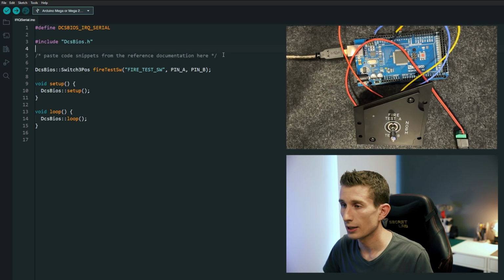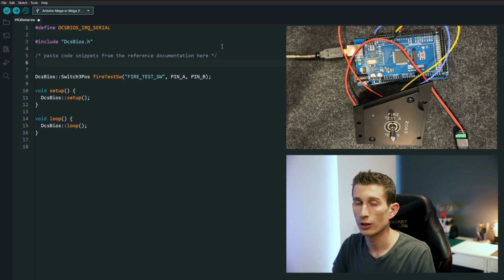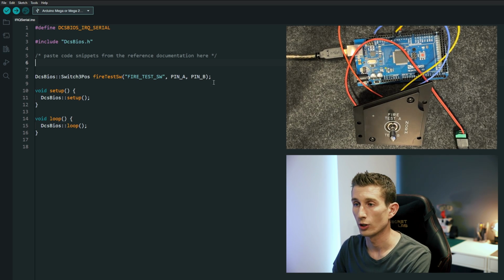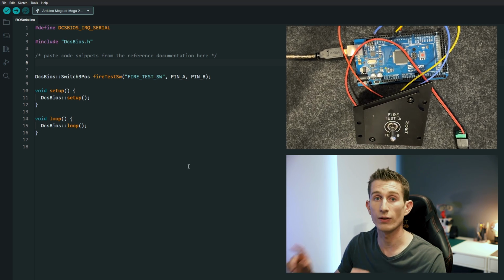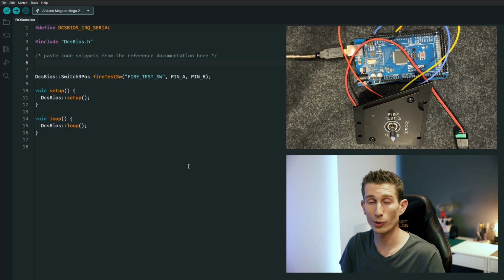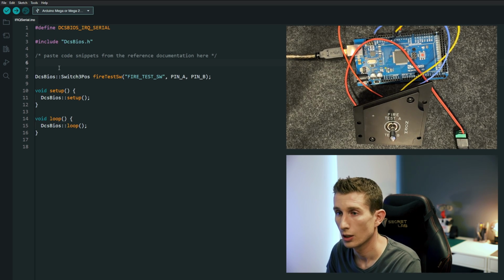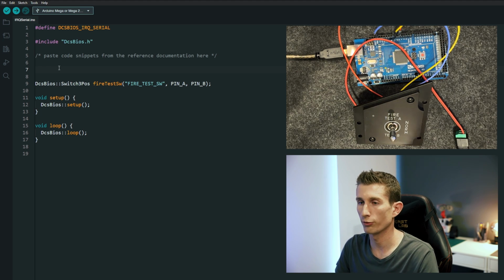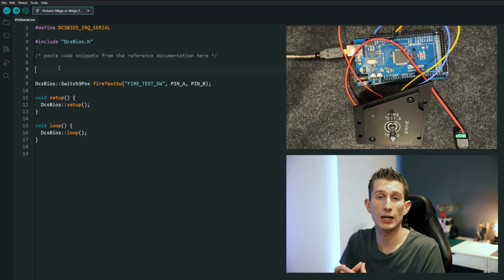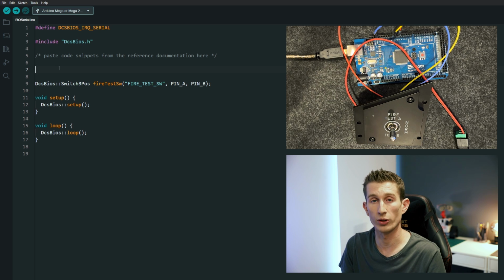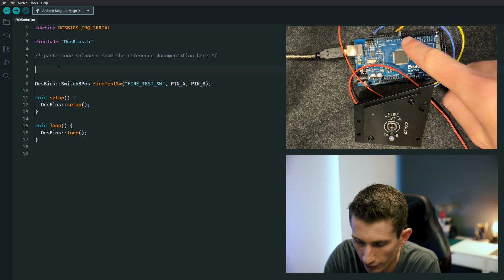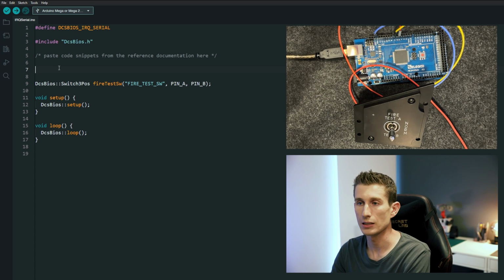Now, what did I say last episode? Do not hard code numbers into your code if you can help it. Because, can you imagine now if we have 200 copy and paste of these snippets and we have just different numbers rattling around, one, you're probably going to forget what the parameters were, and two, you're not going to remember what to delete. So we want to create a variable. We went through that in episode 6, but a quick refresher, a variable is just a little container that stores data that allows us to easily remember what that data packet is. We are dealing with whole numbers, this is pin 7 and pin 5. So we are dealing with integers.